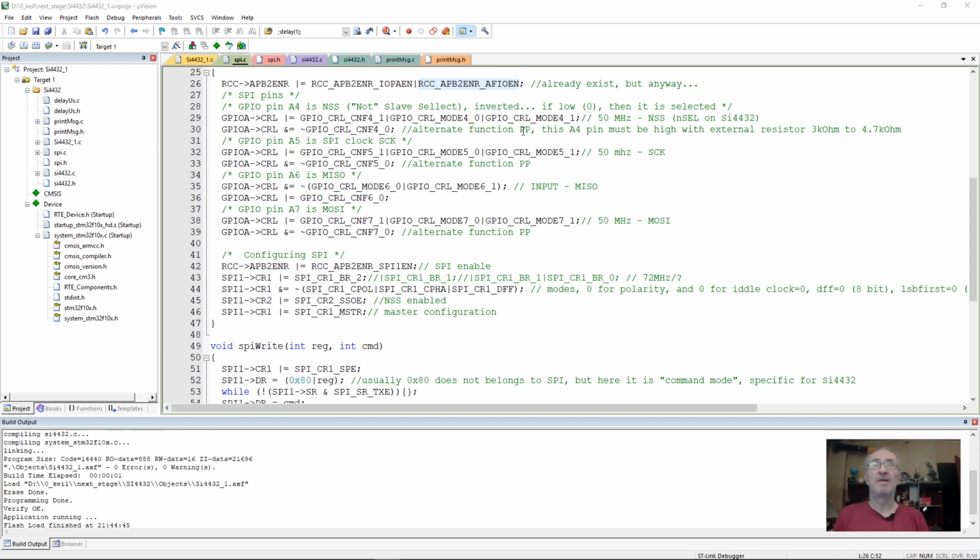Not to forget that there is a slightly confusing part in the documentation about the NSS pin. It says that we should provide a separate pin on the microcontroller, select the chip, then send data. We set this register, and the NSS line is enabled. This is if we want only one sensor. If we want to enable a second sensor, we cannot do that with the same wire. So usually for more than one sensor it is not used, and the device need not be a sensor.